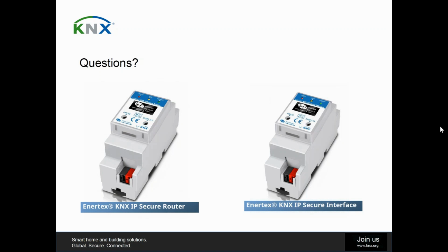But even if it's secured, it will stay open until it is restarted. As I see in the ETS, this is just the standard which says so. But if you program it with the ETS, it will always reprogram and restart the device. So in practical terms, I have to say no, it's not possible, but just because of the ETS, not because of the device.